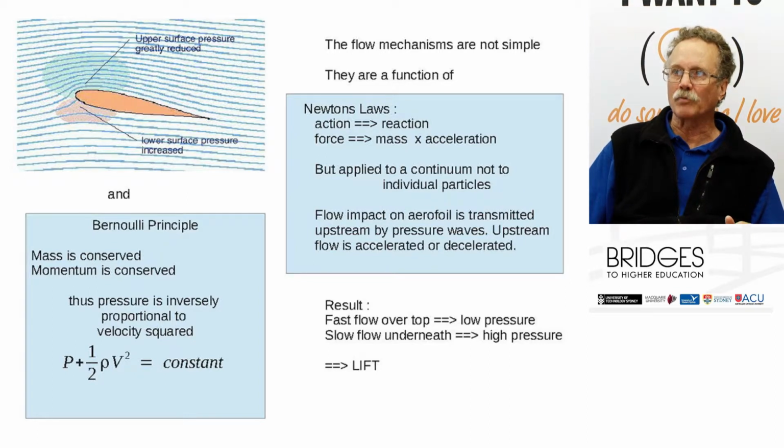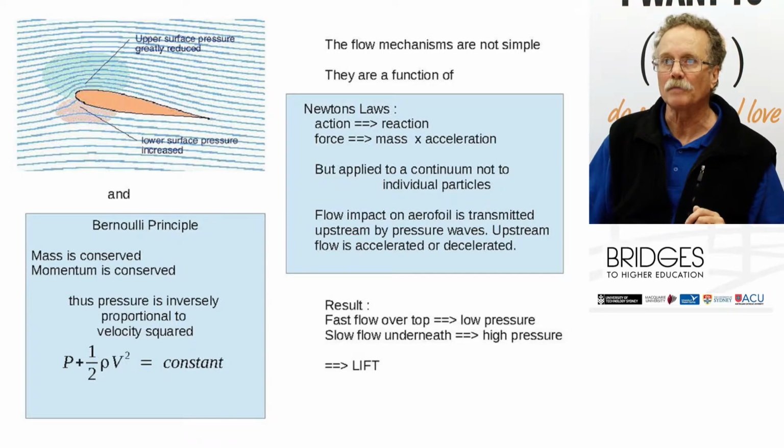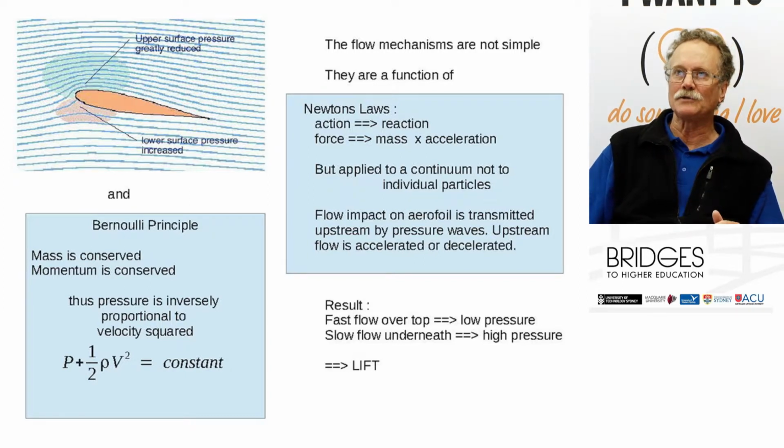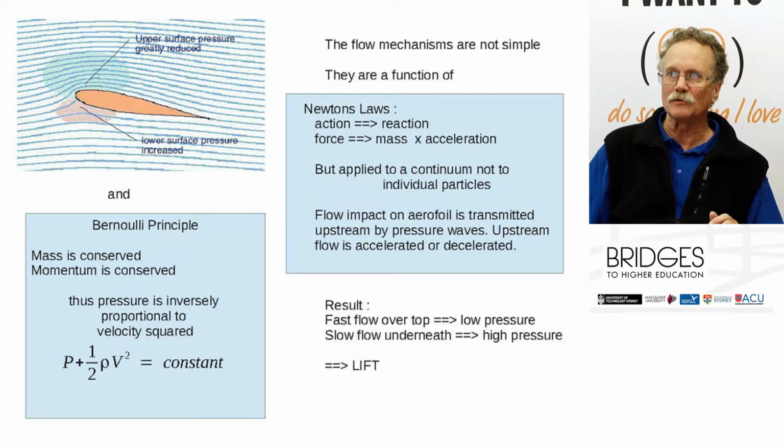Impact is transmitted by pressure waves. Collisions between molecules transmit upstream. Flow coming towards an aerofoil is pushed and produces accelerations. How those accelerations produce pressure changes, we rely on the Bernoulli principle. So if mass is conserved, so the flow coming along here can't disappear, it's got to be conserved. If its momentum is conserved, then there must be a change in pressure proportional to the velocity squared. So Bernoulli worked this one out. It's used in conjunction with Newton's laws.